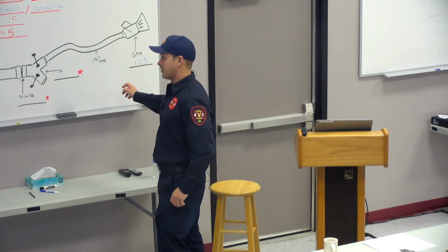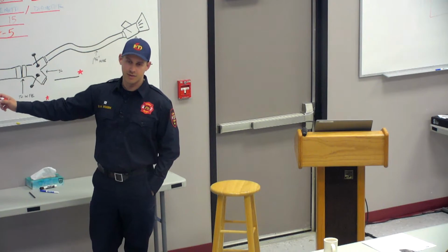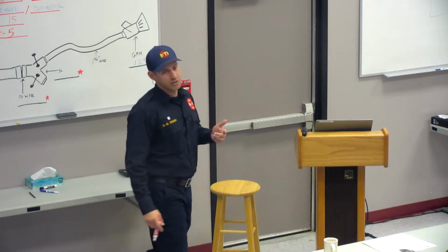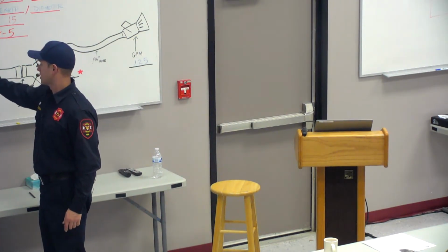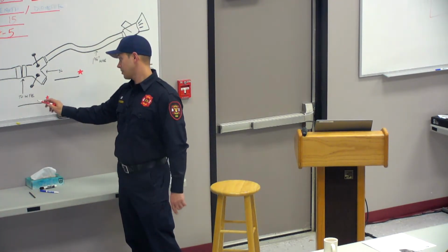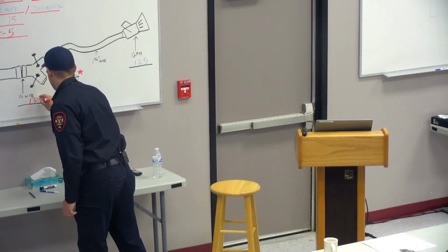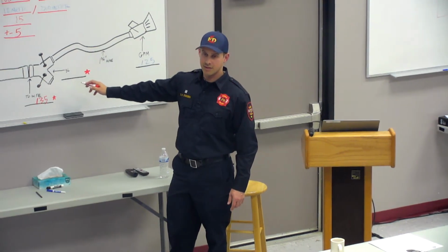We use that 125 to figure out our friction loss on the 3-inch, right? So based on our finger method before, 2 times 2 is 4. So our friction loss is 4. What are we pumping to the Y based on my calculation up there? 135. 135. What's our set loss for an appliance?